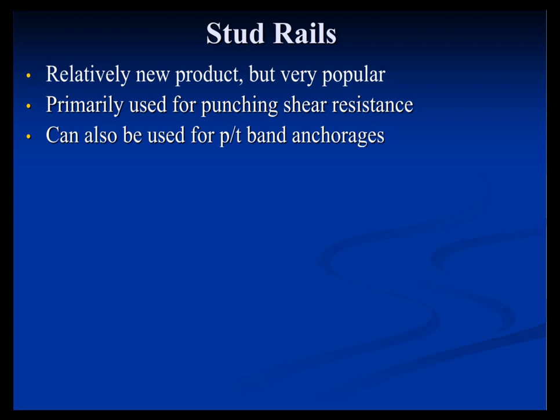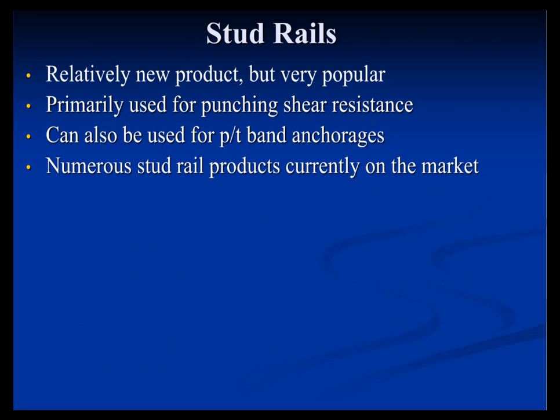They're easier to install, and they don't have the conflict with the perpendicular rebar that a U-bar will have. But the interesting thing is they're not really shown that way in the code, even though they are primarily used for all slabs less than about 12 inches in my neck of the woods. So if you do see that, it's a very typical use. For PT, obviously you wouldn't use it for rebar in that condition, but it's a very popular way to do things.